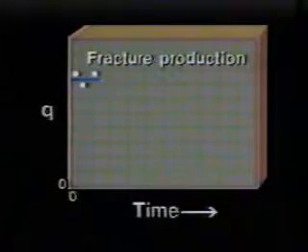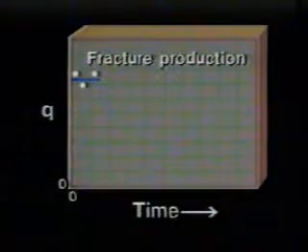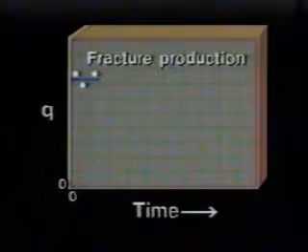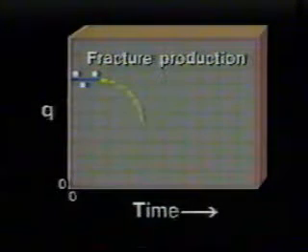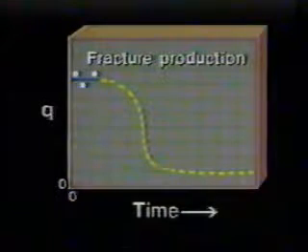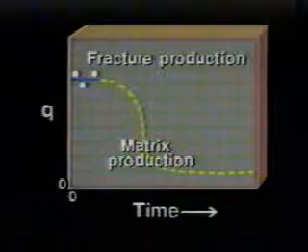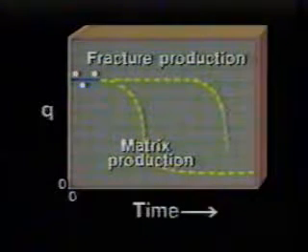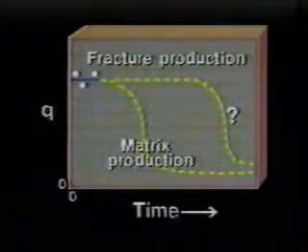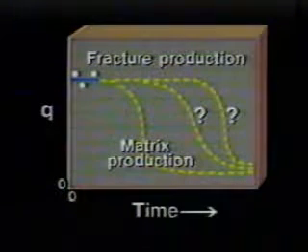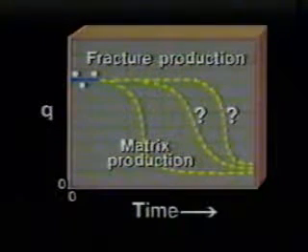Fractured reservoirs provide a special problem for decline curve analysis. During the early stages of production in these reservoirs, a well will produce at a reasonably high rate while the fracture zones are being depleted. The production rate will drop off substantially as the rate of production from the tighter matrix into the open fractures begins to control production rate. The time at which the production will drop from one level to another and the rate of production after the drop has occurred are usually not known.